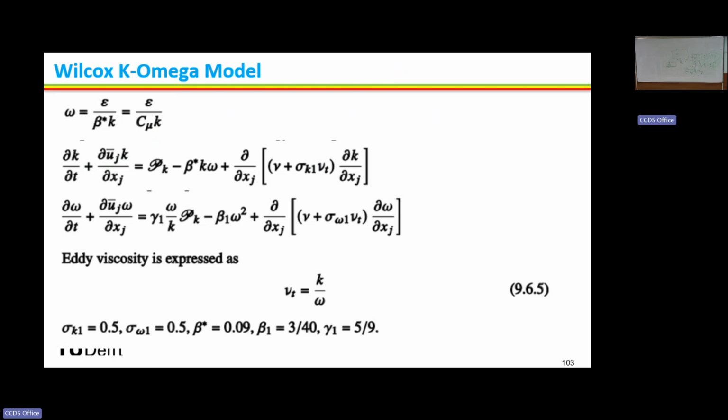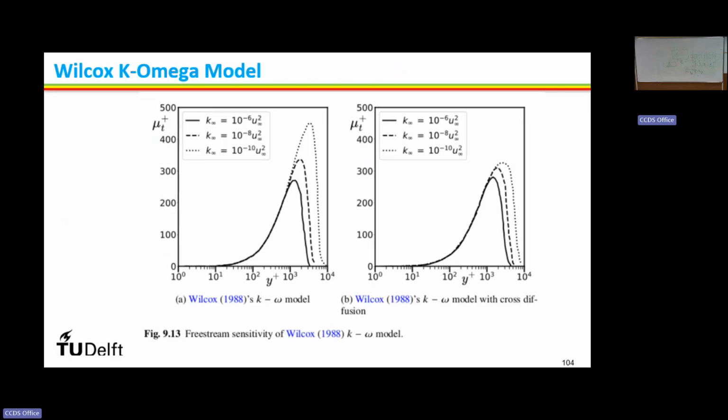But what is the issue with this model? Wilcox developed this model. This model performs well close to the solid wall, but is extremely sensitive to free stream velocity. So let's see what is free stream velocity, right? Suppose this is my flat plate.